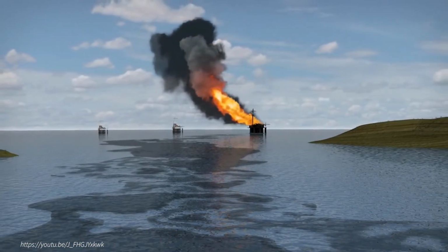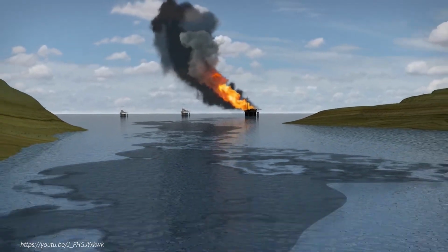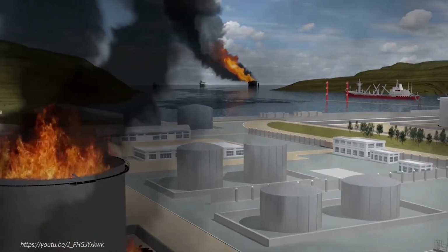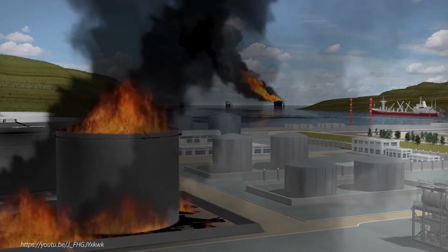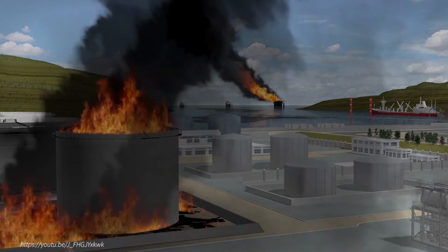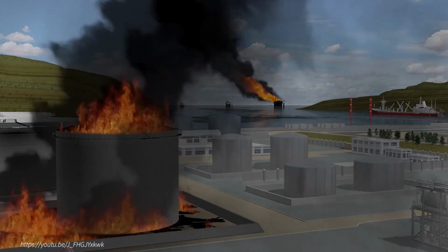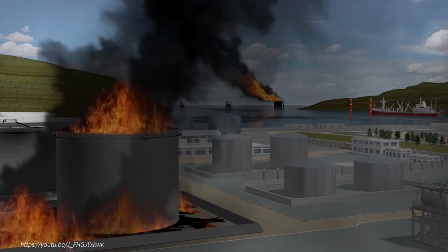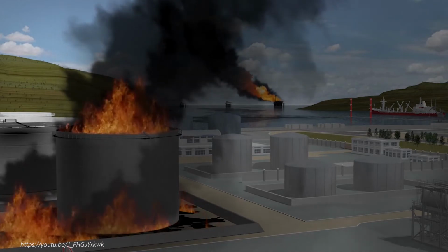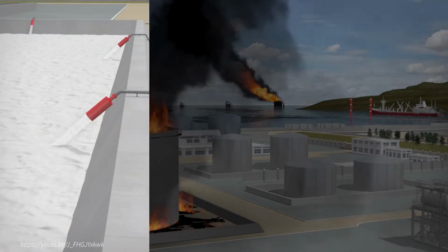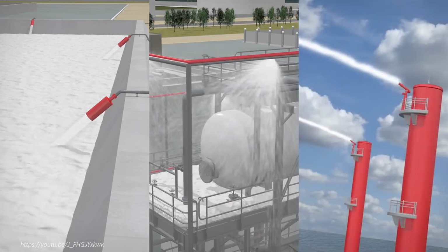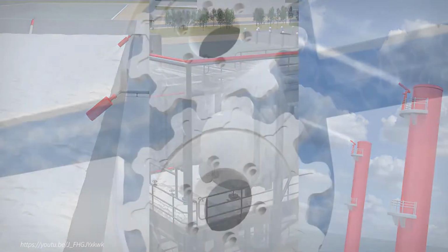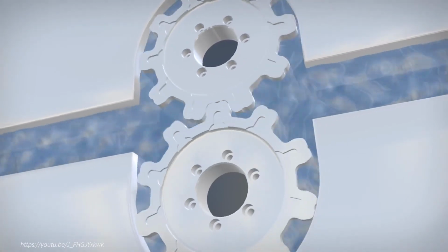Offshore and onshore operations involving hydrocarbons and other hazardous products always face the risk of fire. Adequate protection measurements are of vital importance to avoid large-scale environmental impact and devastating loss. One of the most effective ways of fighting fires in the industry is using foam systems. These foam systems depend on special equipment to guarantee the correct foam-to-water mixture rate. This can include foam pumps, which traditionally come with some challenges.